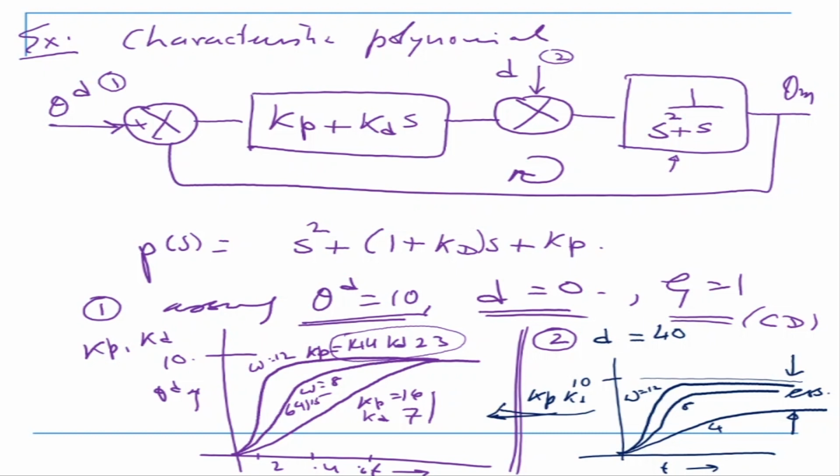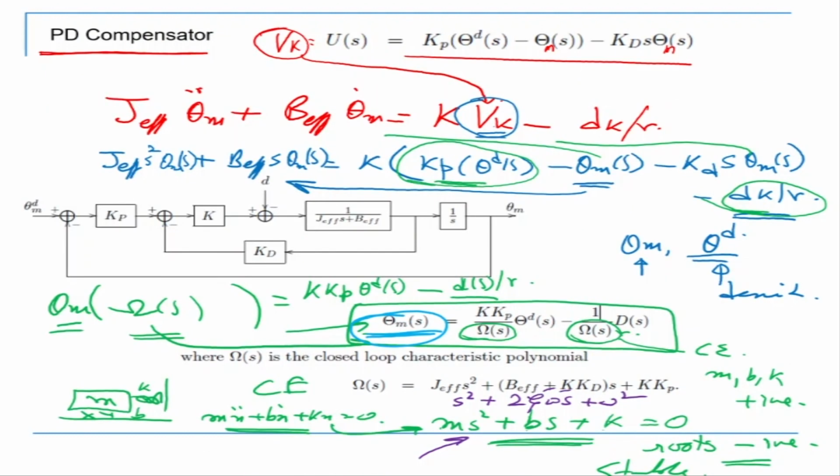Okay, so this basically shows us how you design a control system. When you say PD controller, what does it actually mean? What we are basically seeing is that when we say control system design, it basically means I need to find what is this Vk. Okay, this is my controller, which is the Vk. And if it's a PD controller, I'm going to design my PD controller, put it in here, then find the characteristic equation, look at the stability of the characteristic equation, and then look at the steady state error. Okay, that is the meaning of it.